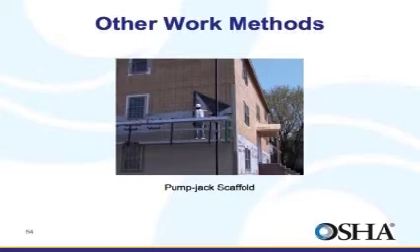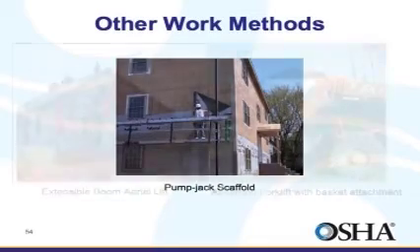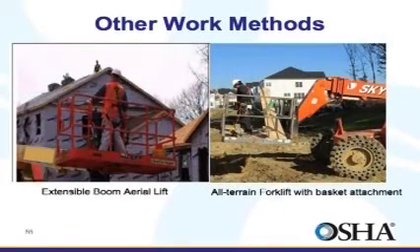Pump jacks are another popular system used by many contractors to install building wrap and siding. Some contractors have used different variations of the pump jack that allow them to jack it up to just under the fascia and to be used as catch platforms. There, the system can be used as perimeter protection while sheathing and roofing operations are performed. An aerial lift is a good alternative for reaching heights if properly used. They can also be used to install and remove guardrail and safety net systems.